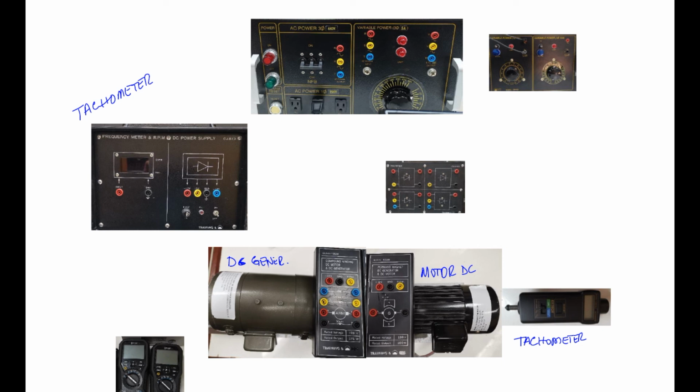Now, to excite either the motor or the generator in terms of field winding, we need the variable DC. The first variable DC is for the motor, because we need to start from 0 RPM toward the rated speed of the motor or generator. We'll check the speed afterward; I think it's written on this nameplate here.